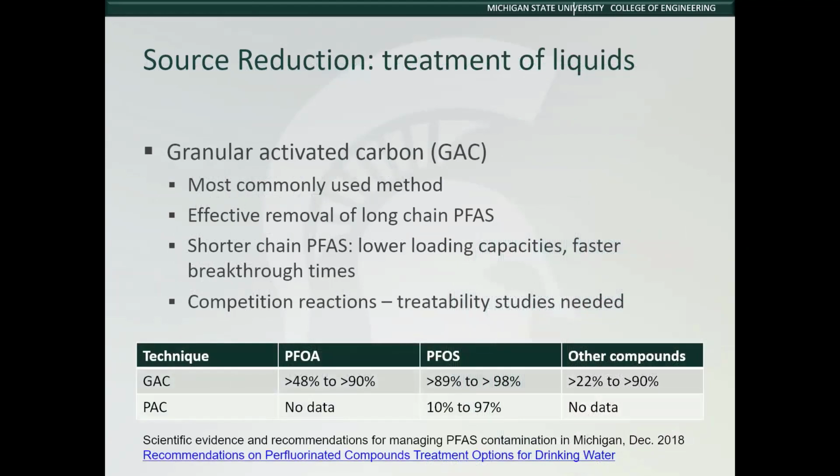Now let's look at the treatment technologies. The most commonly used liquid stream treatment method is granular activated carbon, or GAC. It is effective for the removal of long-chain PFAS. For shorter chain PFAS, lower loading capacities result, along with faster breakthrough times.